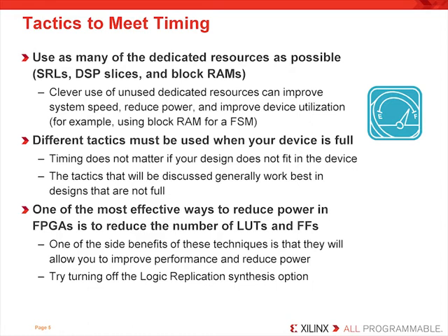Ideally, your FPGA should have device utilization around 85% or less. This works well since the tools have space to move the logic around. Often, this is possible when you port some of the design's components to the dedicated hardware that you weren't planning on doing.